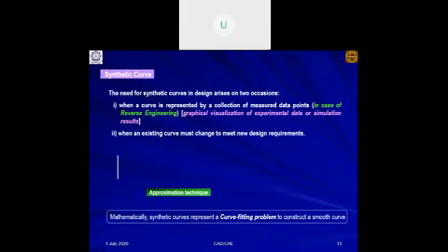You fit the curves or synthetic surface through the data measured using the CMM, and you get the sculptured surface, then may convert it into a solid. After that, with a traditional manufacturing process or additive manufacturing or 3D printing, you can print it. So that is another application of synthetic curves or surfaces for reverse engineering.